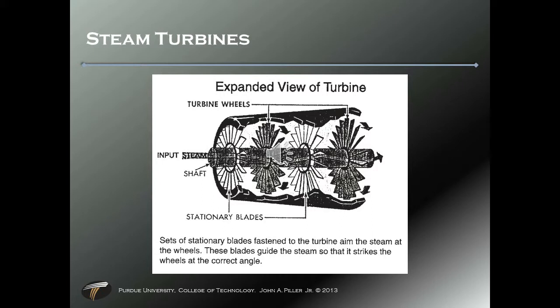Also think back to when we talked about synchronous generators and synchronous motors. Synchronous motor speed is dependent on the frequency of the current that goes into the armature. In this case, a generator, it's the reverse. The speed of the rotation of the shaft determines the frequency of the current pulled off the armature, right? So we're very interested in the speed that the turbine rotates, and we need to maintain a constant speed. How do we maintain a constant speed? We maintain a constant flow of steam into the turbine, and that is done via some type of governor which compensates the speed to maintain its frequency.